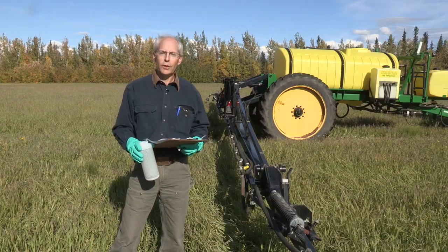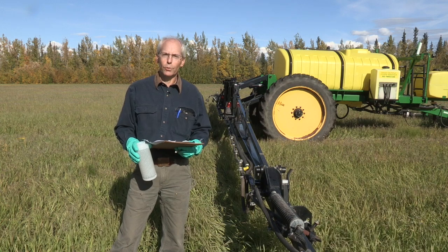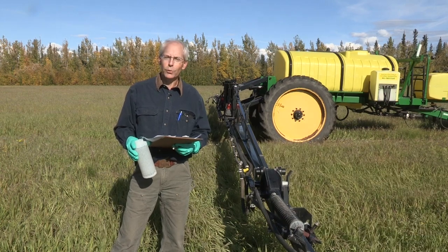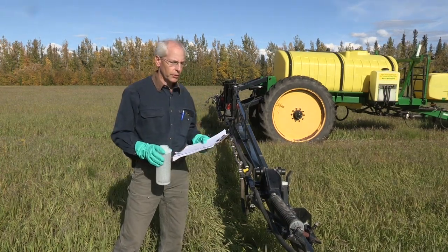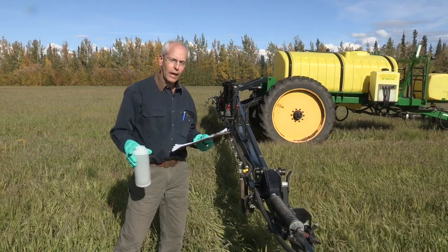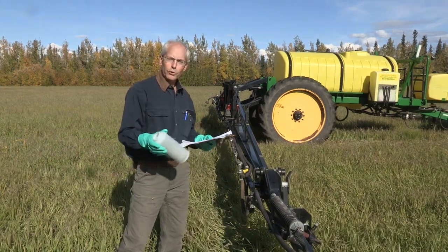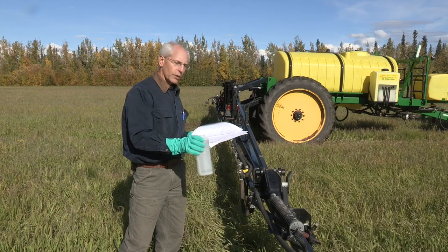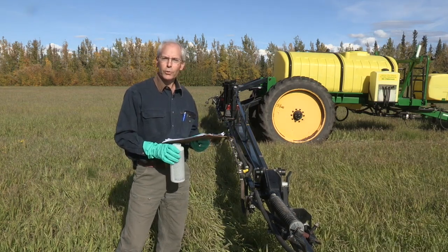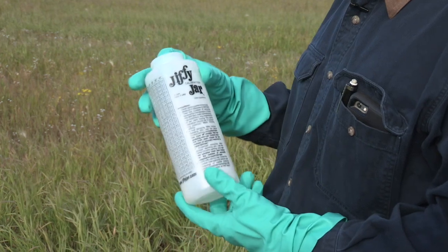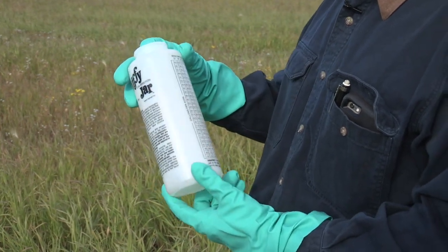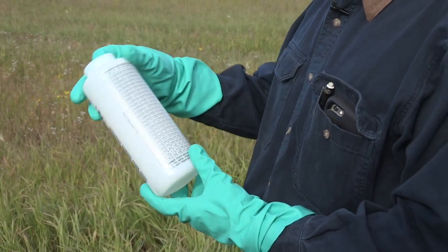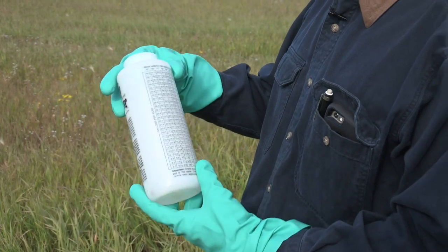So now that we've made several timed passes across our 204-foot course, we averaged those times and came up with 29.74 seconds. So with the machine stationary and operating at the same pressure as during the test, we will hold our utensil under a nozzle to determine gallons per acre. Then we will check several other nozzles up and down the boom to make sure that they're within 10% of each other. We happen to be using these Jiffy jars, but there's other brands of utensils that use this 1/128th of an acre calibration methodology. And they're handy.